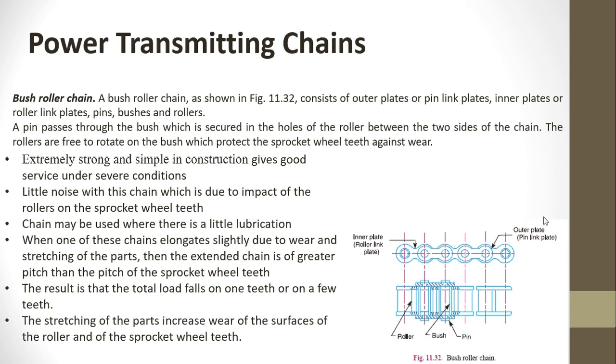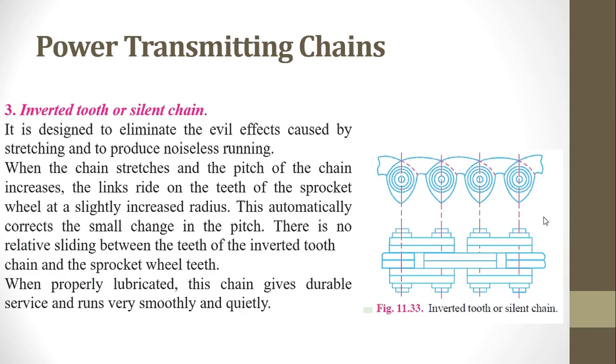They are very good from the transmission point of view. They don't have much noise as compared to the previous ones and they need lubrication, but the lubrication is not aggressive, and the wear and tear of these types of chains is less. One more thing is that they are quite self-adjusting also. So the next chain is the inverted tooth or the silent chain.